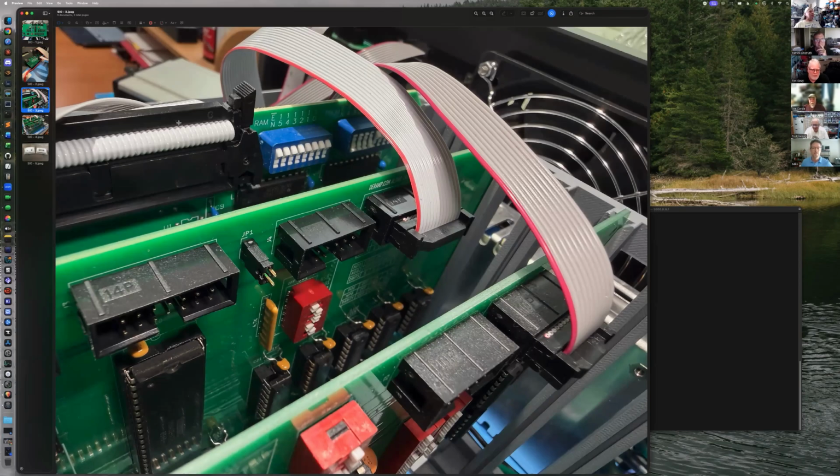Literally, you just make up a 14-pin connector on each end. That's JP1 there on the left of the connector. If you don't want 5 volts going through your cable, you just pull that jumper. There's a jumper here that you can turn the 5 volts on and off. It's really simple to use, and as Patrick keeps saying, it's a miracle it worked on the first prototype.